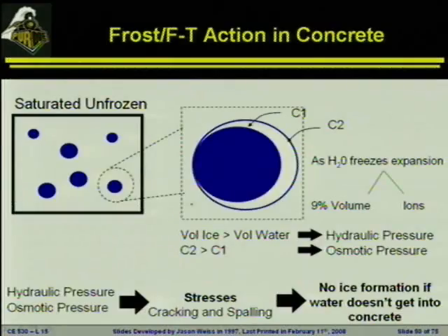One of the things I'll mention real quickly here before we end up today is I want to talk a little bit about some of the freezing and thawing action. There are two main features that are going to cause this pressure that generates inside of the concrete. The first one we know is the hydraulic pressure. That's simply the fact that the water is going to expand on freezing. This is the hydraulic pressure that we're talking about, the 9% increase in volume.